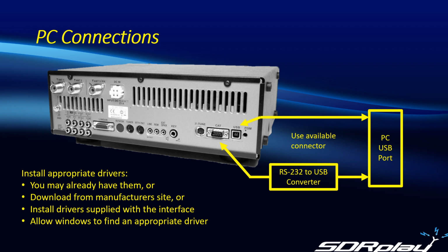In addition to the hardware connection, you do need the appropriate drivers. And the good news is, if you have already been using some sort of computer software with your rig, then you've probably got those drivers already installed. If not, the manufacturer of your rig often has the drivers available for download. If you're using an RS-232 to USB interface, they will often either provide drivers with the product or link to download them. And finally, and this worked for me on the Kenwood, Windows itself found an appropriate driver for the interface once it was plugged in, which is all well and good.